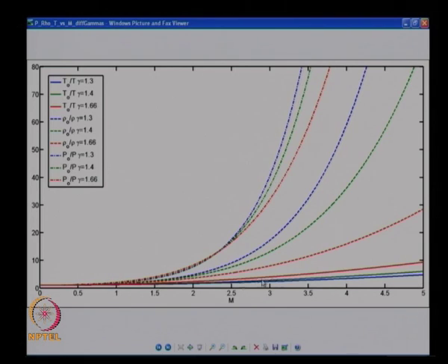And density is somewhere in between, it is supposed to match p equal to rho R T anyway. If I multiply density and temperature, I should get this plot. And there is a glitch here somewhere in the middle. If you look here, this is opposite. The trend is opposite for around Mach 1.5 to 2.3 or so. That is because the temperature has the opposite trend compared to density, and because of that you have that glitch for some time, and after that it behaves like this for higher Mach numbers.